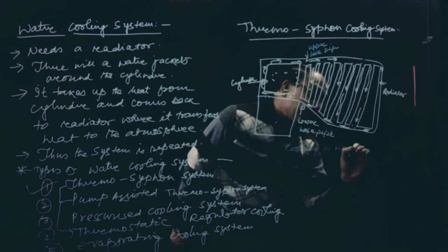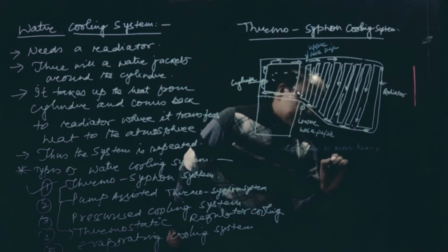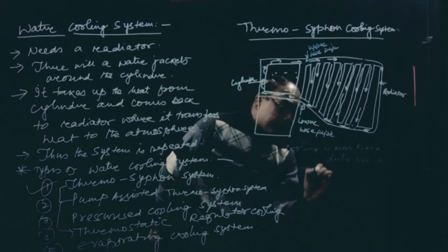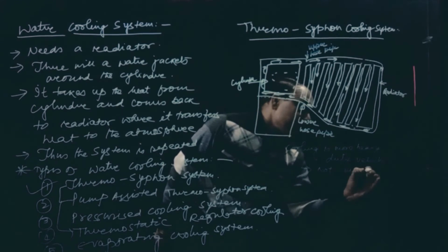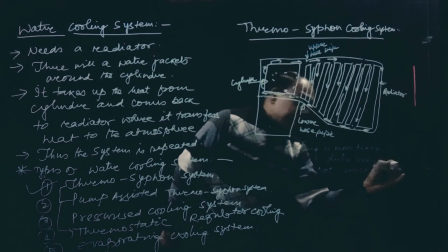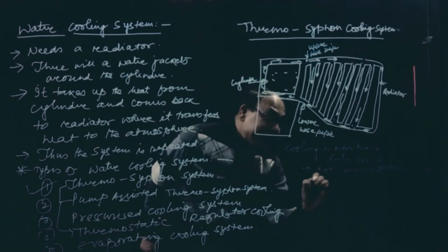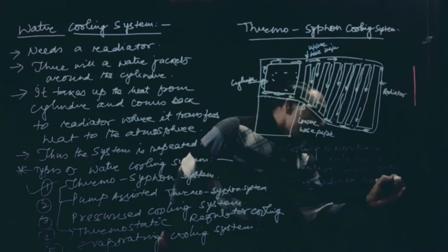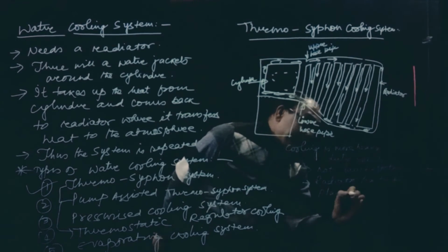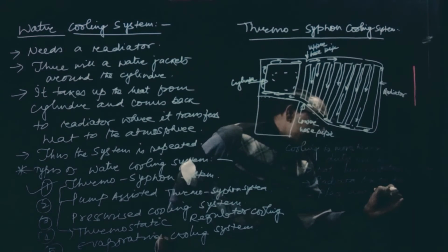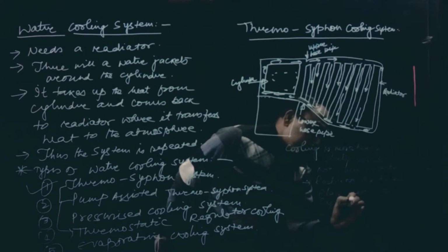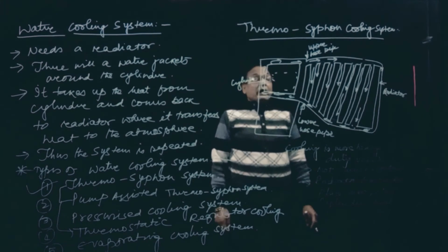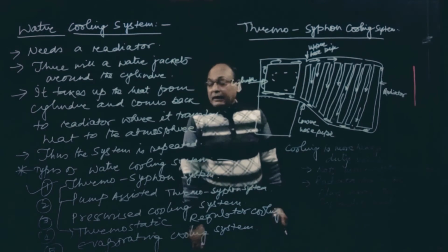Remember it is for heavy duty vehicles, not much effective. Here radiator has to be placed above the cylinder head. So these are the problems of the thermo siphon cooling and these problems are overcome by pump assisted.